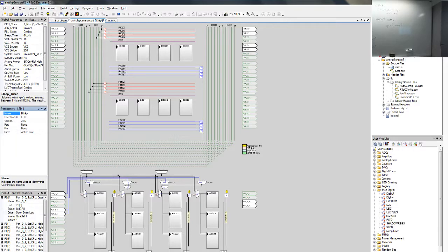So this chip has 3 8-bit ports, and this board has 4 LEDs. So by some wire you should actually be able to connect one of those pins to one of those LEDs. I will use, just for fun, let's see, port 1.5 for example.